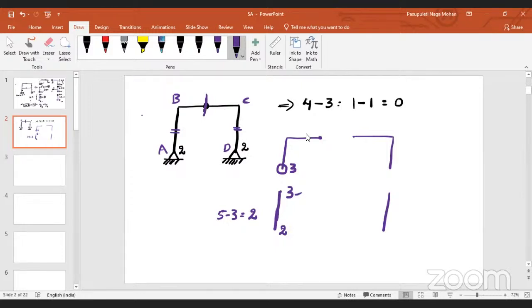As it is a hinge, there won't be any internal resisting moment, so the moment will be equal to 0. So here there will be some axial force and also some vertical force. 2. Now tell me, if these 3 are known, can these be known or not? No. Now how many unknowns are there in this case then? 2 unknowns. Then how many equilibrium equations?